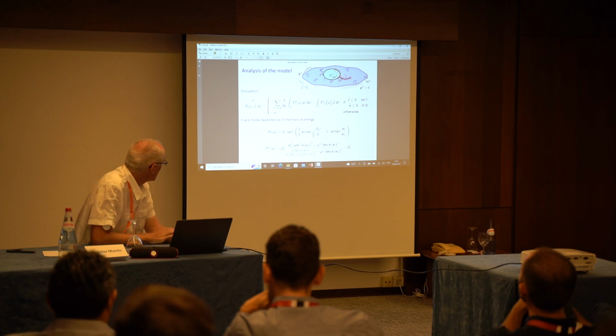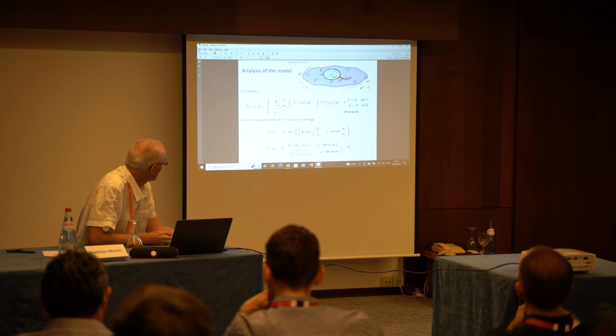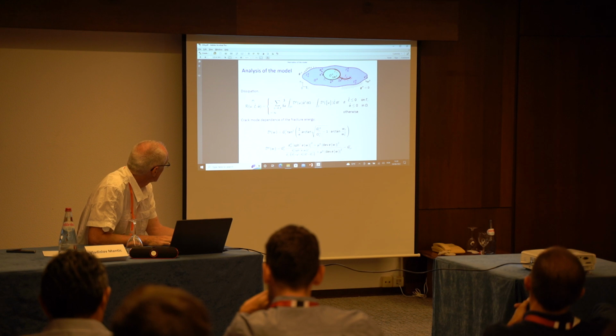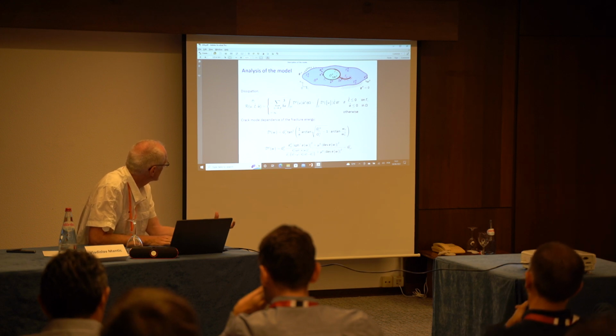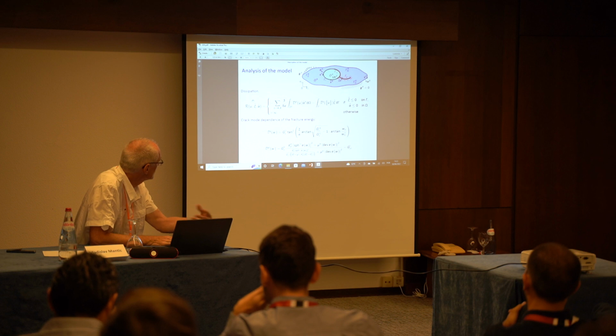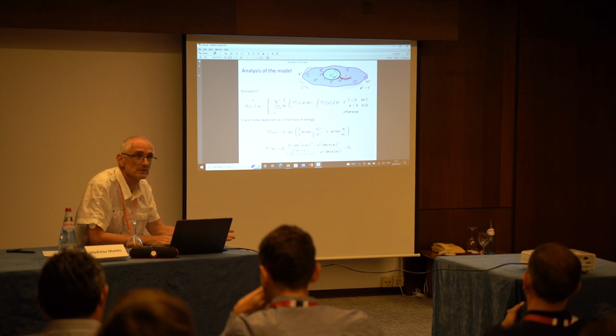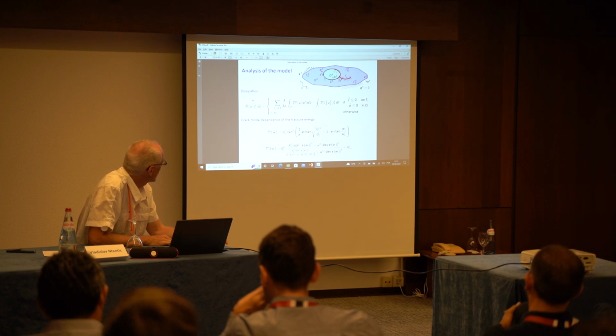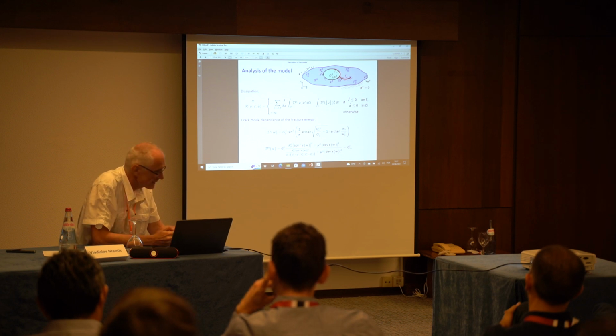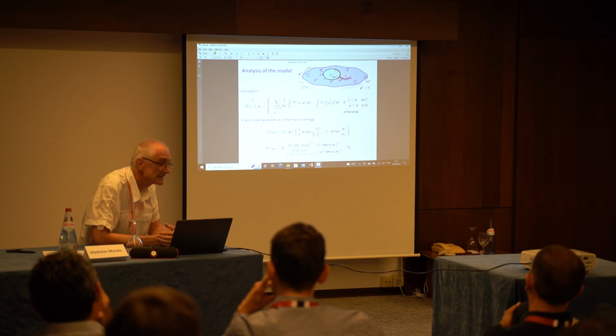So I tried to formulate it in such a way that in shear the spherical part of the strain is equal to 0, so that there will be a difference between GC2 and GC1, which adds some energy proportional to that, which should be released, in fact, or dissipated when it is not strictly the opening mode.